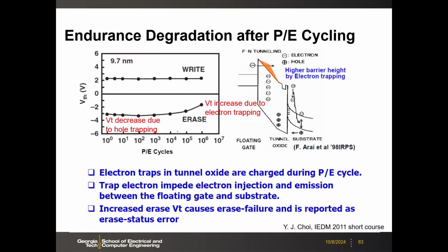All right, so then let's look at endurance degradation first. So how many cycles can you write? Here, this is from some older data, for the 2D NAND in an older technology node, but this trend is general. Here we typically show the PE cycles, program and erase cycles, P and E as one cycle.